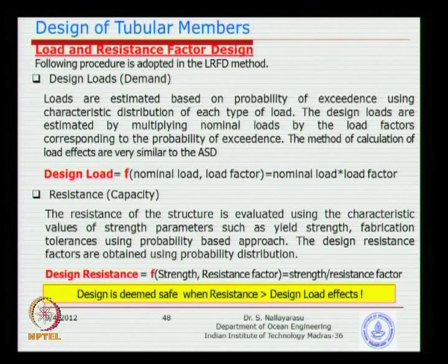That means we need to study the parameters involved, establish the frequency distribution versus the characteristics, and then find out if I want to take 1% risk of exceedance, what load factor should I allow. So you reverse calculate risk versus reward. If I do not want to take any risk, 100%, then you ultimately end up with the allowable stress design.